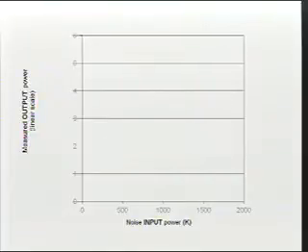Okay, noise figure is about signal-to-noise ratios at input and output. So we're comparing measured noise outputs against noise input power, and that's most conveniently expressed in Kelvin in equivalent noise temperature. On the output side, it doesn't really matter. It's arbitrary instrument units. But both of these are linear scales, and both of these, when we start to populate this diagram, everything has been done using realistic numbers.